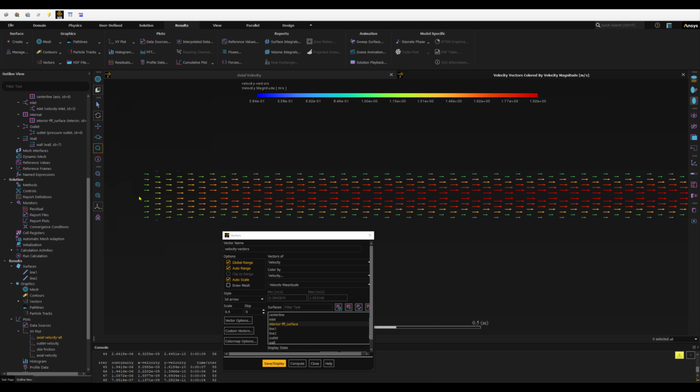So the velocity vectors provide a picture of how the flow develops downstream of the inlet. As the boundary layer grows, the flow near the wall is retarded by viscous friction. Note the sloping arrows in the near wall region close to the inlet here. You can see. So this indicates that the slowing of the flow in the near wall region results in an injection of fluid into the region away from the wall to satisfy mass conservation. Thus, the velocity outside the boundary layers increases.